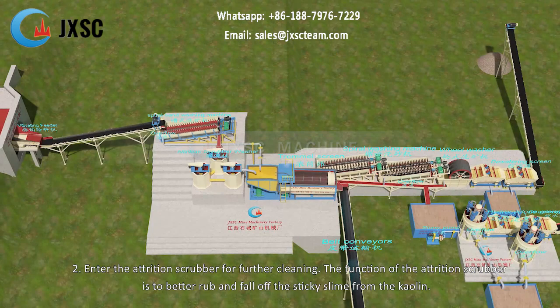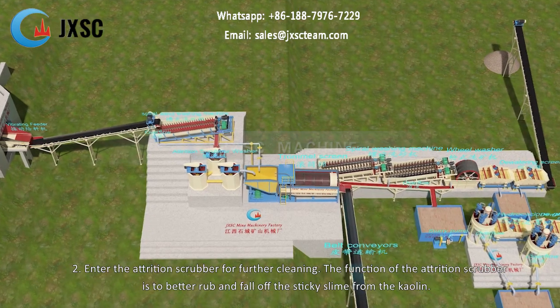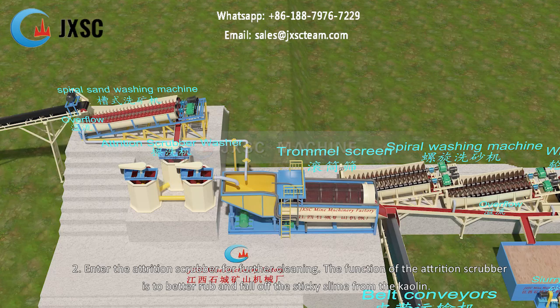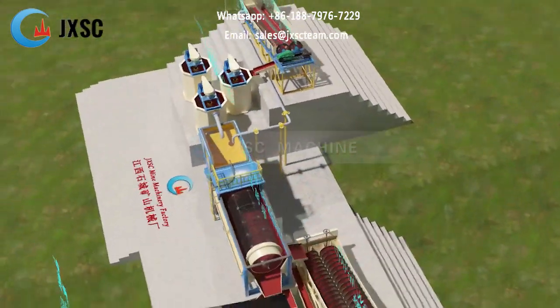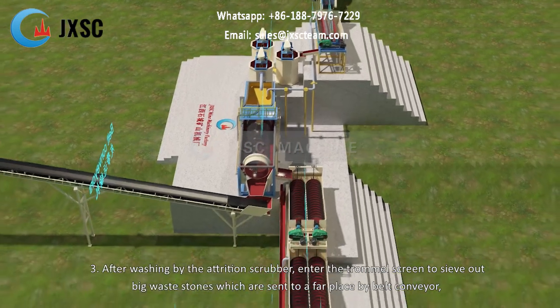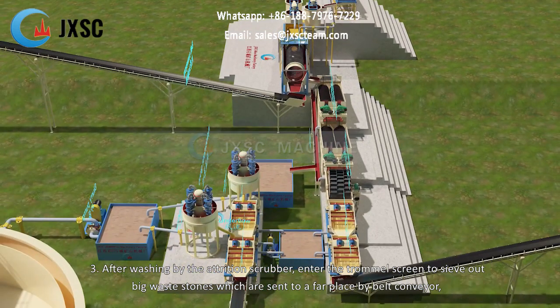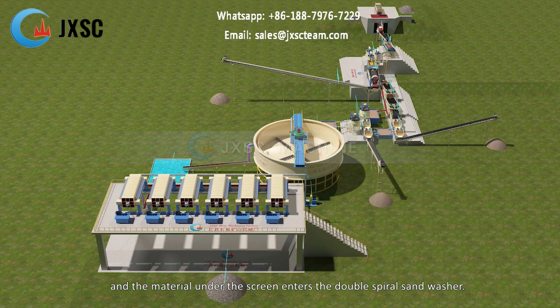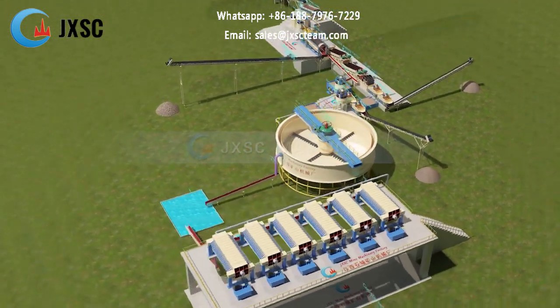2. Enter the attrition scrubber for further cleaning. The function of the attrition scrubber is to better rub and fall off the sticky slime from the kaolin. 3. After washing by the attrition scrubber, enter the trommel screen to sieve out big waste stones which are sent to a far place by belt conveyor, and the material under the screen enters the double spiral sand washer.